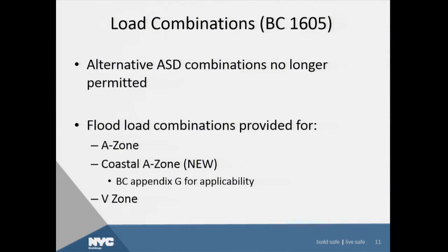And you'll see there's also specific mention of a new type of flood zone called a coastal A zone. You'll be hearing more about that when Joe Ackroyd, my colleague, starts talking about the applicability of coastal A zones during his talk. Right now, it's a new requirement here in New York. It's not necessarily applicable just yet, but our code does reference it at this point.